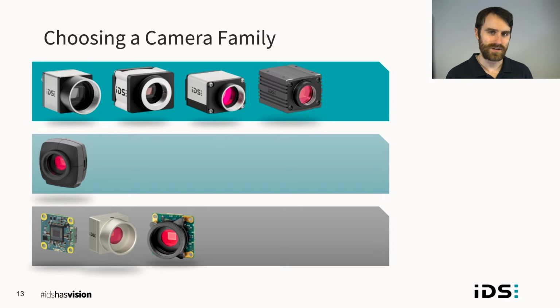There is no image memory on board, so as a sensor is capturing an image, it wants to send it straight away to the host. And that means if there are any collisions on the bus, as there can be with multi-camera systems, that image could be lost. In addition, these sensors are MIPI based and have a microcontroller instead of an FPGA as the kind of logic controller on the camera.